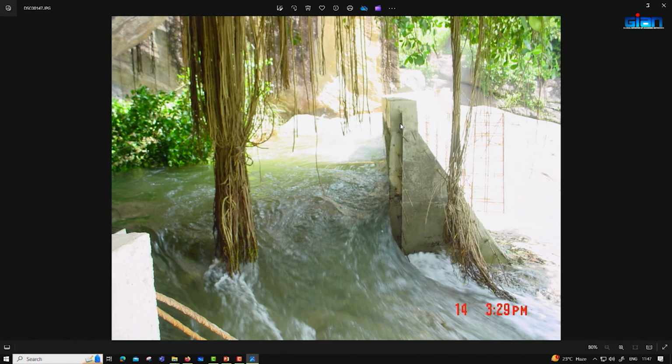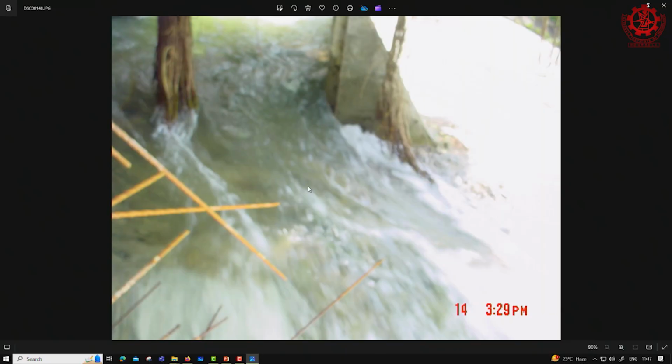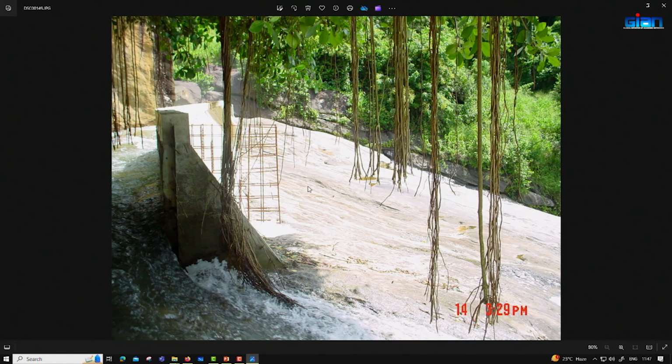Here you can see our diversion weir was under construction. This is long along there, but this part has not been closed yet. On a rainy day, you can see the flooding water, ferocious water flows. So, you have to work under very careful conditions when you are working on mini hydros. In the sites you have to be very careful. These conditions are not easy. Same place, with more water. We build the weir on this rock, pinned to the rock.